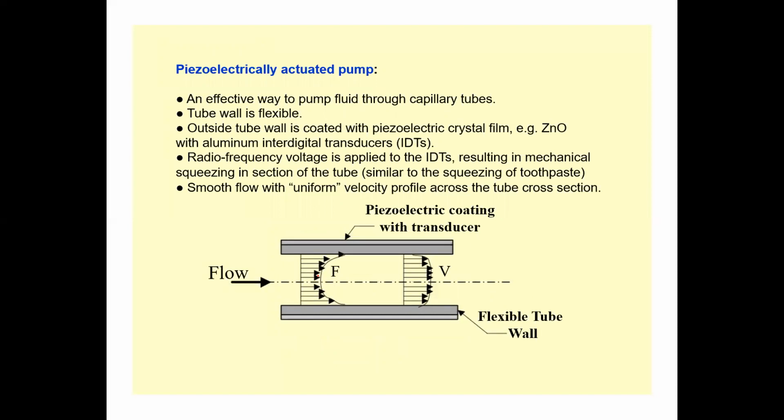There are also piezoelectric actuated pumps. You have a pipe, and on top of that we have the piezoelectric coating, right? We already know that when we apply voltage on a piezoelectric crystal, it can deform mechanically. When you apply a voltage with a certain frequency, it contracts and relaxes with that frequency. It is just like squeezing a toothpaste tube: you press it, and fluid comes out.